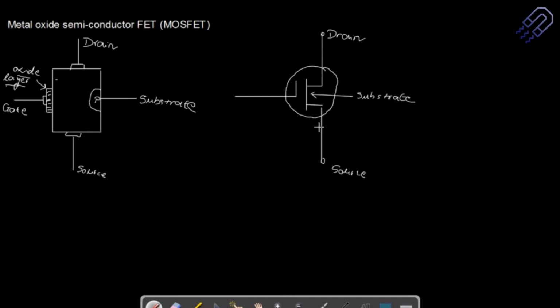and depending on whether it's a p-type or an n-type, you can actually have it. But this is the interesting part. Since this is an insulator, because this is a metal oxide deposited here, this side is one terminal of the gate, and this is the part which is connecting to the n channel. This is an n channel, let's say. So that means this is separating the gate from the channel, and it is acting like a capacitor, because you have some kind of material inside that is acting like a dielectric.